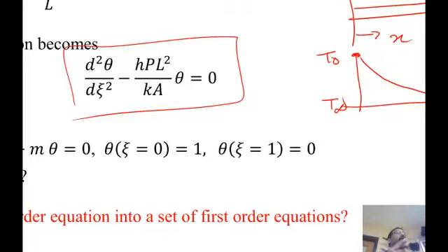Okay, so how do I construct that curve such that it satisfies the differential equation in MATLAB? I'm going to do this in non-dimensional form. What that means is I'm going to redefine some variables such that this solution can be used for any fin that you design, as long as the conditions of constant k and constant A are met. Any length fin, any thickness fin, etc.